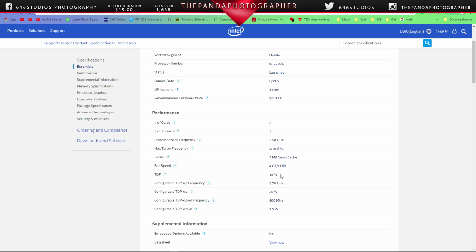So the estimate is around 25 to 30 millivolts undervolt if you're going to use the Intel Extreme Tuning Utility. I'm reading it right here, the frequency is at 100. Yep, around 25 millivolts. So go down negative.